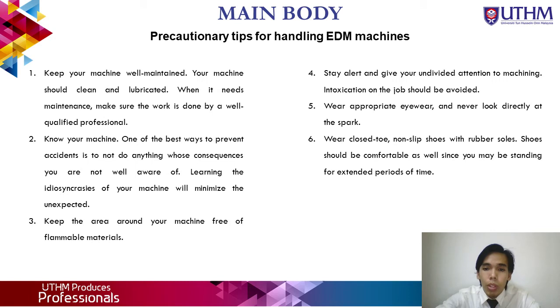So, for the precautionary tips for handling EDM: first, you must keep your machine well maintained. Your machine should be cleaned and lubricated when it needs maintenance. Make sure the work is done by a well-qualified professional. Second, you must know your machine. And third, keep the area around your machine free from flammable material.